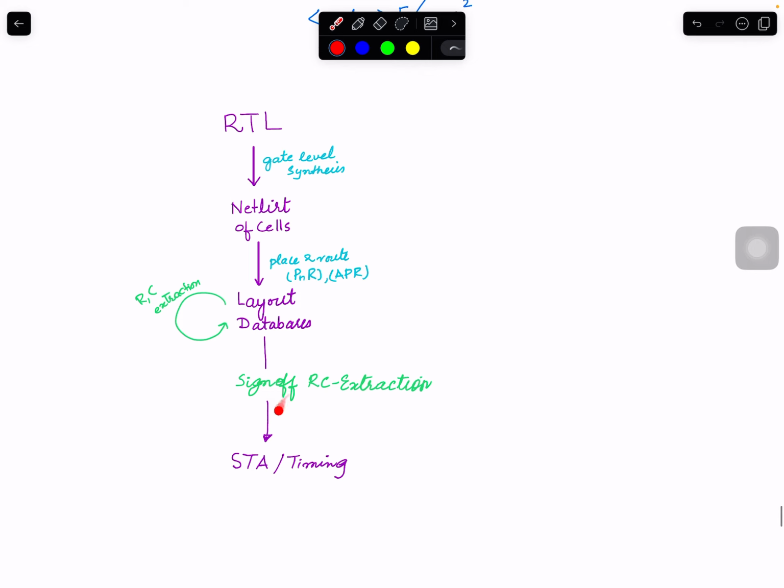And then that information comes into a static timing analysis tool such as PrimeTime in the form of a SPEF file, which has all those smaller components throughout the length of the metal. And then STA will simplify the model, lumping different capacitances together to come up with some sort of graph that is analyzable in timing. So that is the process that we do.